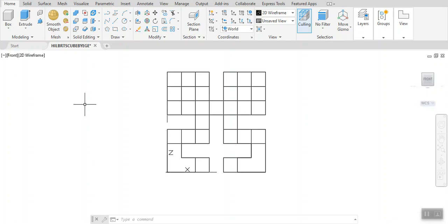One of them is your name. Another one is company name. Another information is the name of the drawing, dimensions, and the front and the orthographic views that accompany all that in a certain order. So title block can be done automatically by using the command called MV setup.